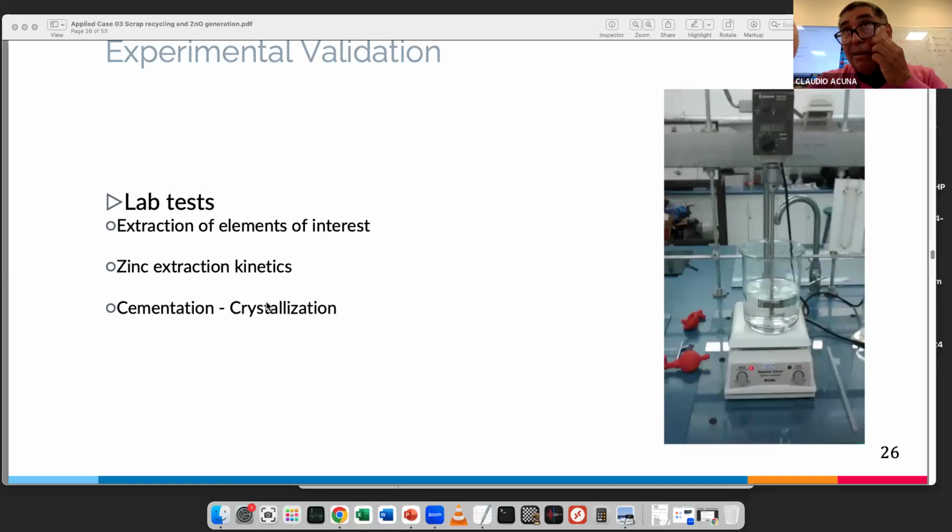It's always going to be better if you have a larger unit and you extract a very little amount in order to have samples. 5 points is fine. 3 is not good. One of the students in the Erasmus thesis had kinetic data with 3 points. This is not good. 5 points is the minimum. Okay? Got it? Agitated reactor, be careful with the materials.